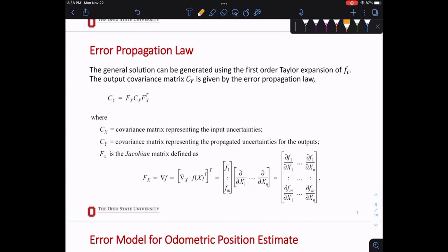So now the Jacobian will be that function f that we created that had the current position plus increment in position change with respect to different variables, right? How many variables we have in our function? 5. X, Y, theta, delta SR, delta SL. So the distance that the right wheel moved and the left, because if you have something in the structure of the wheel drawn, so you are getting the differentiation with respect to that as well, right?